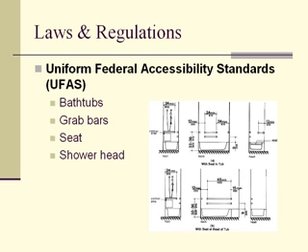At the same time, the shower head. The shower head has to be 60 inches minimum, and basically that allows for a greater level of access for somebody using the shower than just having a fixed shower head. So that element always has to be there. Another element is the controls. The controls, you can see there's a little hatched area, a dotted line that says control area.